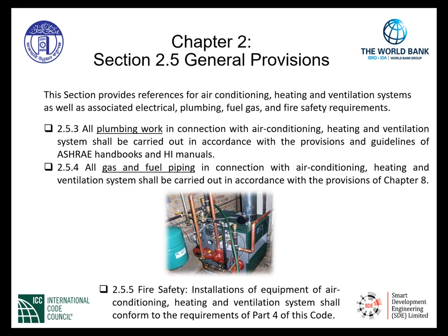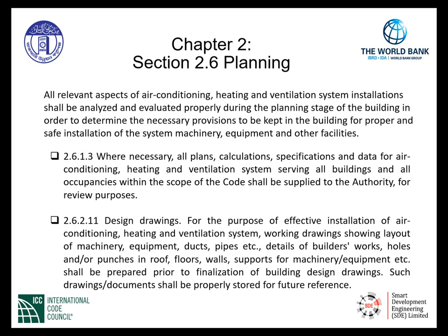The last section here, Section 2.5.5, deals with fire safety and indicates the following: installations of equipment of air conditioning, heating, and ventilation system shall conform to the requirements of Part 4 of this code. Again, giving some direction to fire safety requirements of the equipment that is related to air conditioning, heating, and ventilation systems. Planning. Section 2.6